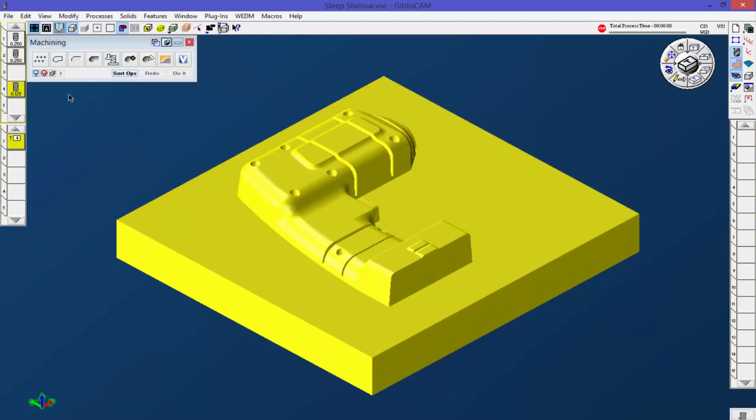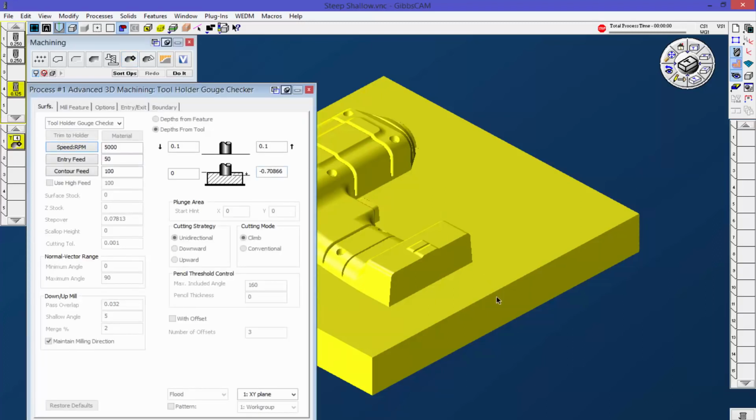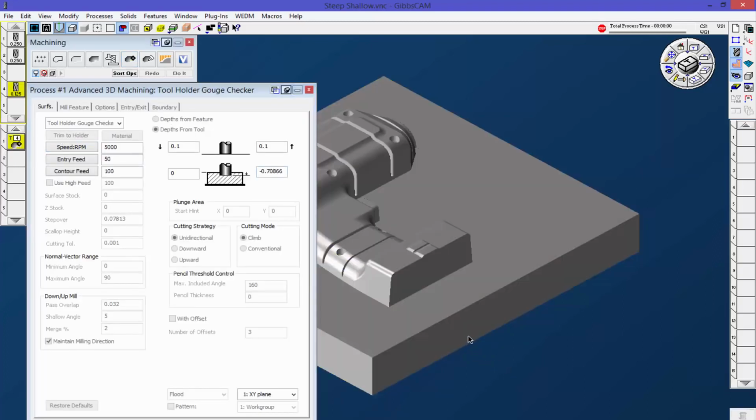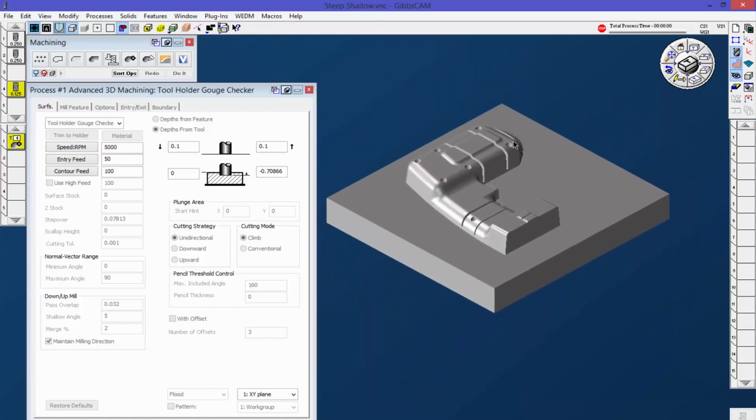All right, let's go ahead and talk real quick about the toolpath splitter. What I found when I was doing parts that were convex, where I want the tool to go up and over a part, is I really like using an end mill, not a ball mill, for a couple of reasons. The biggest reason is the center of a ball mill doesn't actually cut, whereas the center of a flat cutter will.